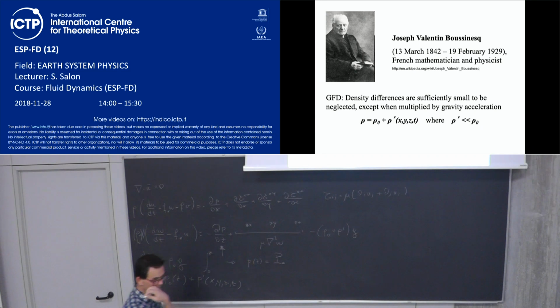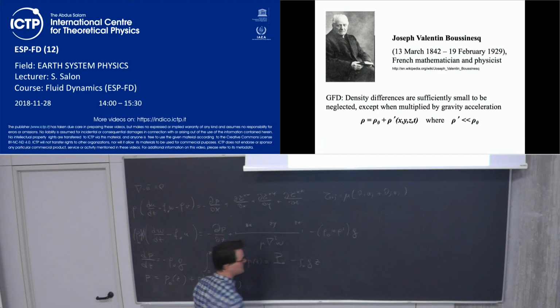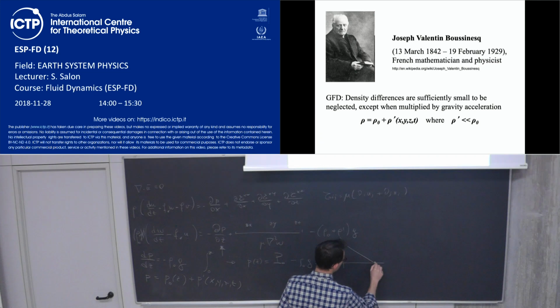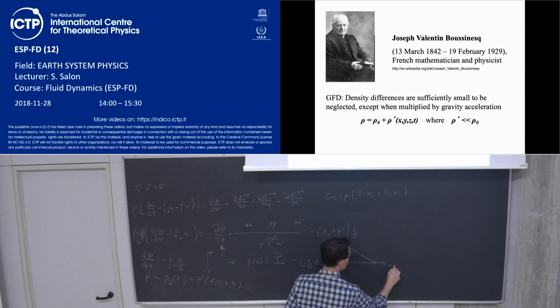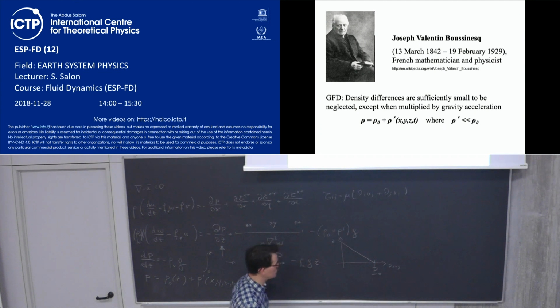It's just the integration constant, nothing more than that, minus rho 0 g z, okay? So this is the expression of the hydrostatic pressure, which actually tells you that if we put z here and the pressure here, this will be my reference pressure at z equal to 0, which is actually the surface pressure at the sea level, if you like.